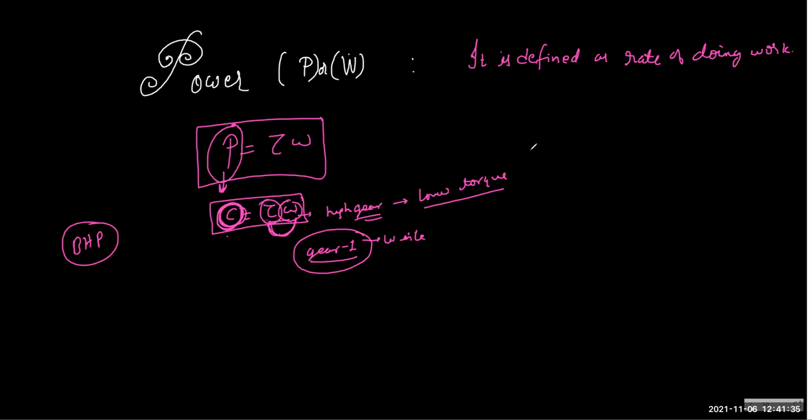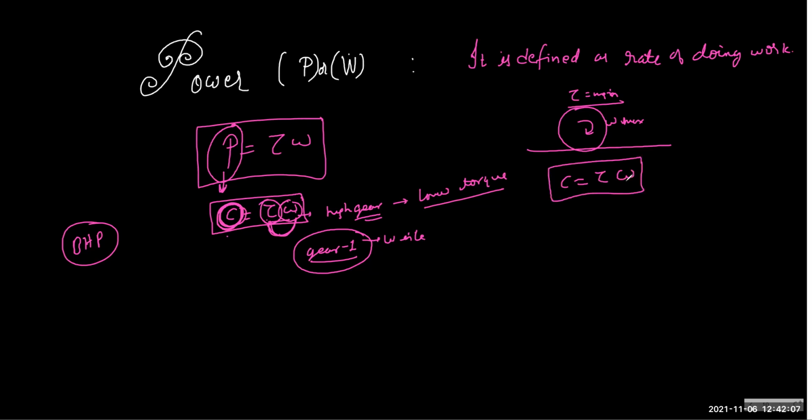But if you're on a flat road, we are not trying to overcome some gravitational force. So on a flat road, what we need is just inertia to continue. So the highest gear will make the omega maximum and torque is minimum, but the product is constant, so your car is producing power at a certain rate. By minimizing the torque, I can maximize the omega because I have the choice of manipulating these two, and that is how we achieve the high speed.